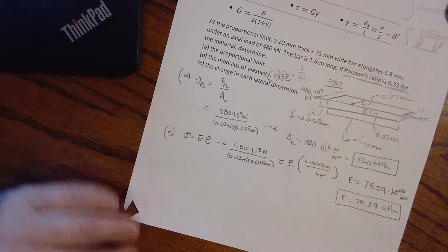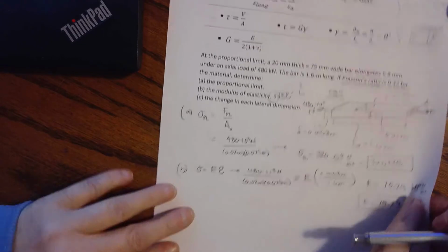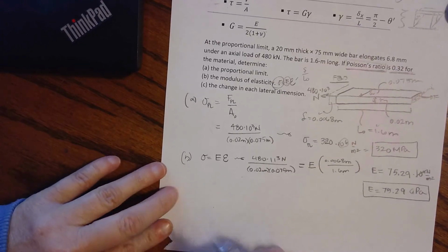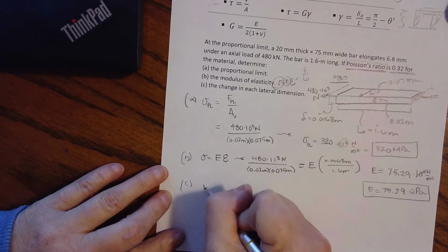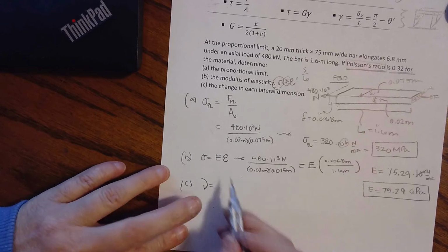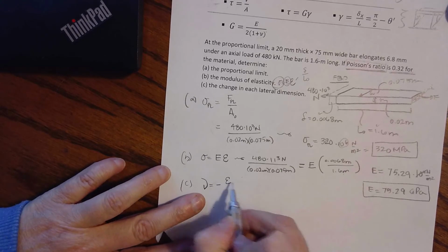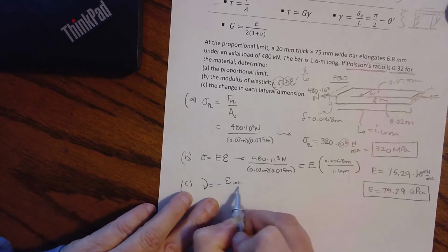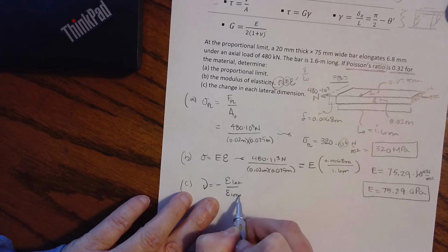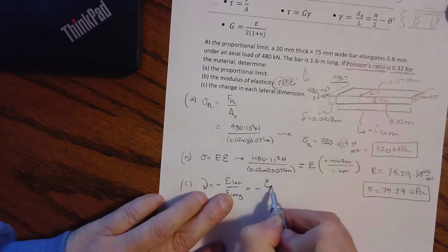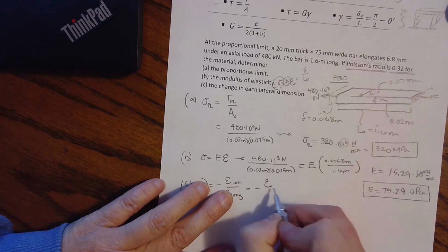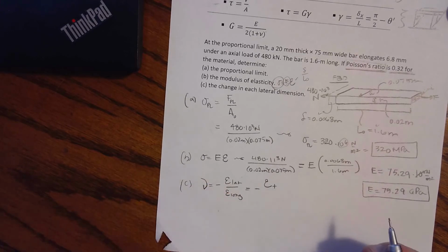Okay, now it says the change in each lateral dimension. So if I want the change in each lateral dimension, that is where I use Poisson's ratio. And Poisson's ratio is negative strain lateral divided by strain longitudinal, or you could call it strain tangential. Remember that means